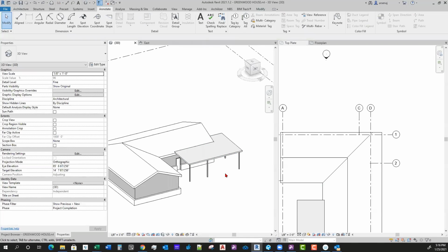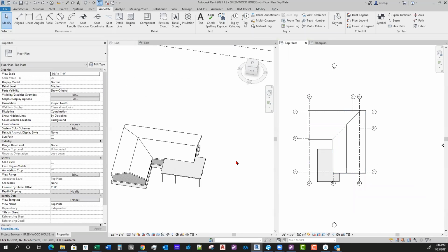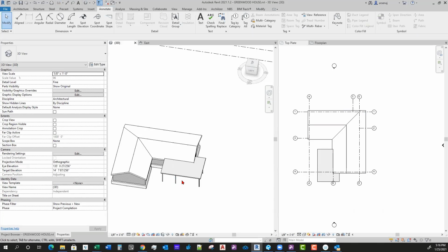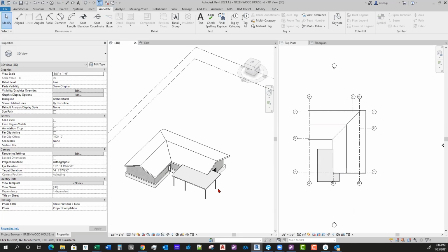Yeah, I had a garage roof. So it's like a small another peaked roof coming out from underneath a long, wide main roof that was actually taller than the garage roof too. So when I built the garage roof, like I said, I did it to the footprint of the entire garage. So it built that shorter roof underneath, running completely underneath the other big roof. So it wouldn't let me join them at all. I had to make that roof to where it was only like a 2-foot wide roof pointing right up at the point at the front of the garage, and then basically extrude it back into the other roof. And it let me do that. Okay, cool.